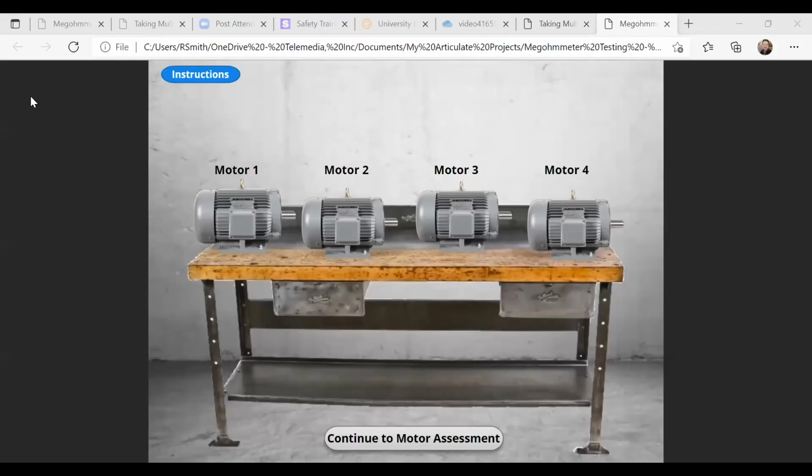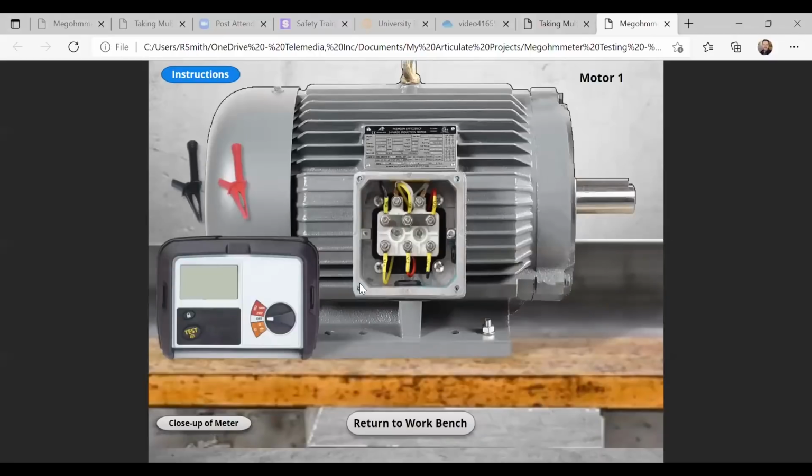And this one, basically the magic of using megohm meters for your use. So if you have a motor, let's say 4 different motors you're going to test electrically on the workbench, and you take a look at any given motor, using this tool correctly on getting into the junction box and attaching your alligator clips and really knowing what readings you should be getting for ohms on this setting, or mega ohms, and pressing the test button on this setting between phase and ground, and getting these readings and understanding what they mean. You practice that in a class for sure. And there's a lot behind it. There's NFPA 70B has a lot of best practices on how to troubleshoot motors and what to look for from the readings for mega ohm meter tests.